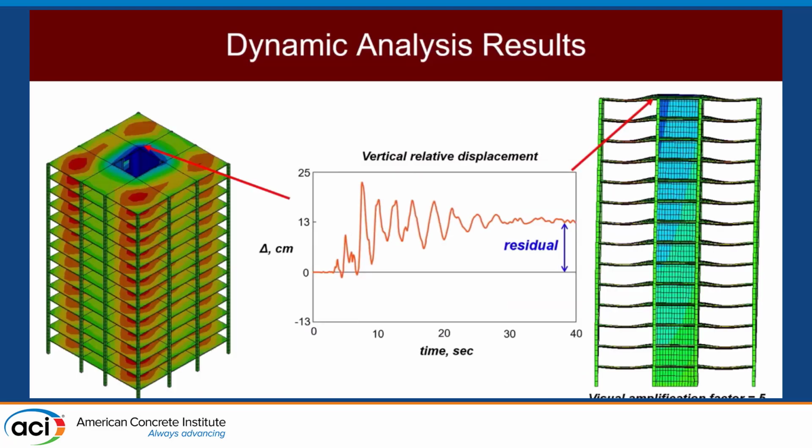And then also with that, back to that tension and compression chord, maybe I should have switched those slides, sorry. This is showing that the residual displacement of the structure can be very important when you're modeling, and being able to get an accurate representation of that can help determine whether or not you're able to repair the structure after all this damage has occurred, after your maximum considered earthquake.